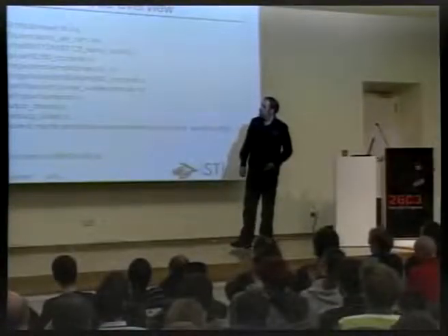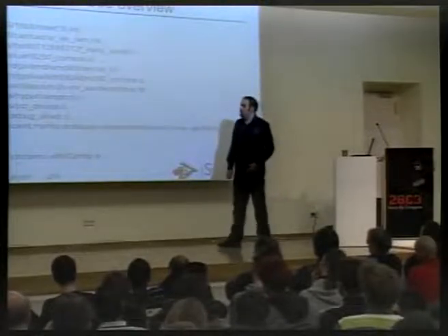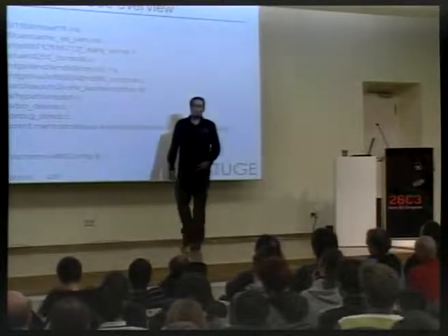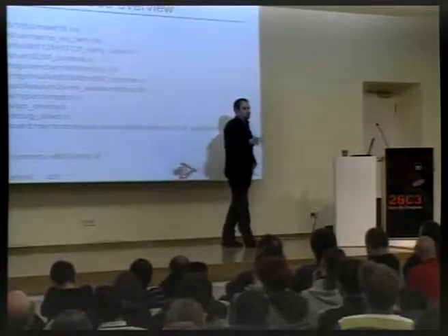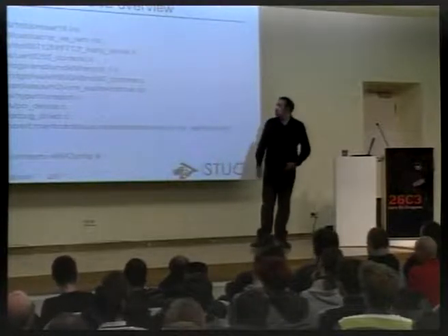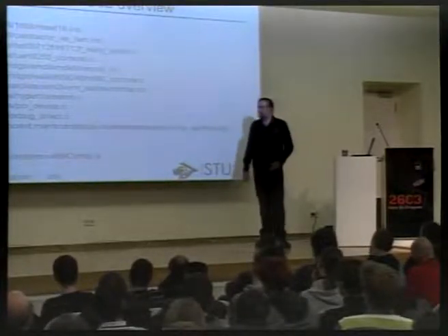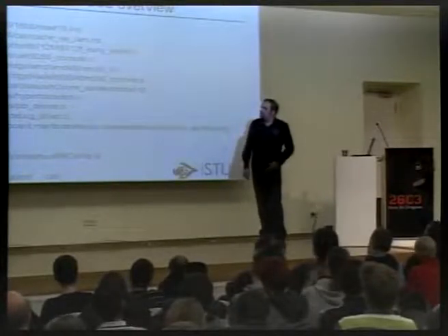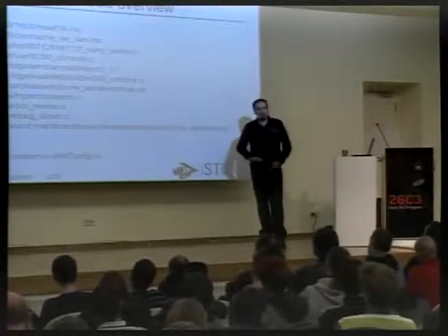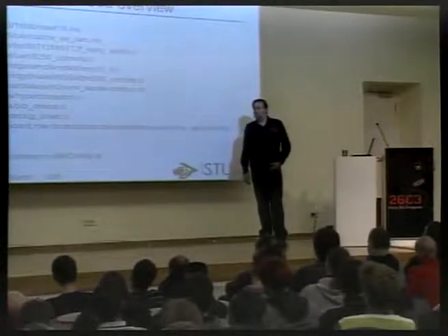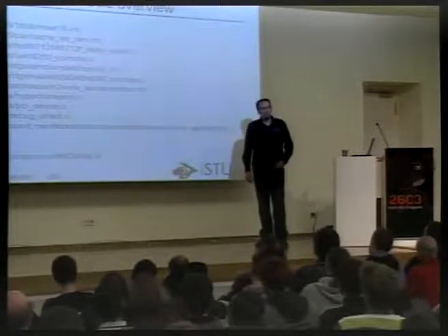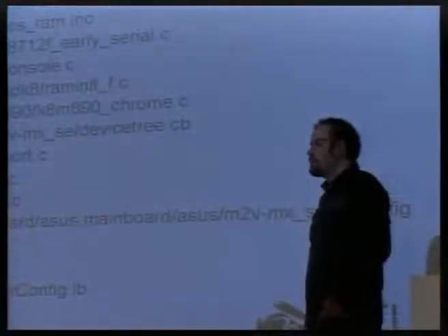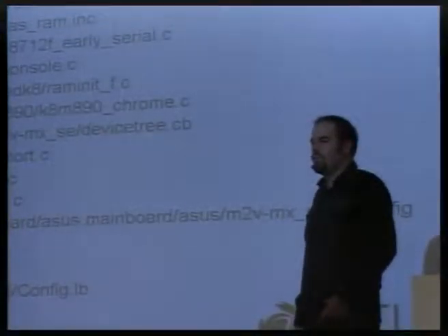And later on, we get to run through the generic hypertransport code, which sets up all the hypertransport connections in the system, the links between the CPUs and links from the CPU to any other bridge, be it Northbridge or Southbridge. And the same goes for PCI devices, of course. All the PCI buses need to be enumerated, and there's some code there in devices, PCI device, to check for what's on the bus, what's connected to the bus, and to set it up so that it's working.